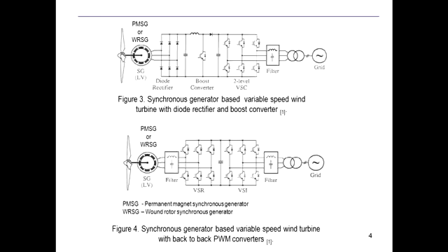We have a three-phase rectifier, which we call a PWM rectifier, which produces a voltage across here, and power is extracted from the wind turbine, and it goes through a filter, and then we produce a voltage here, and that voltage is higher than the peak-to-peak voltage here. Okay, so we call that voltage source rectifier or PWM rectifier. And then we have an inverter producing three-phase sinusoidal output, and we connect to the grid.